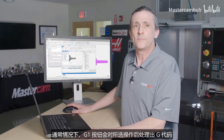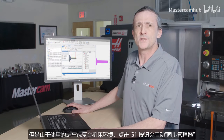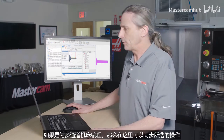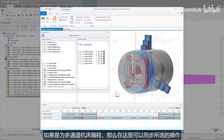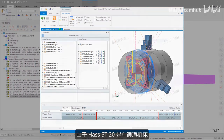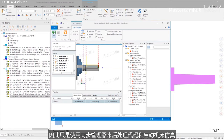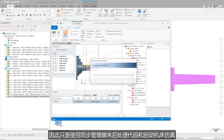Normally, the G1 button would post out the code for the selected operations, but since I'm using the mill-turn machine environment, the G1 button launches the Sync Manager instead. If I were programming for a multi-stream machine, this is where I would synchronize my operations to avoid machining errors or collisions due to conflicting turret movement. Since the Haas ST20 is a single-stream machine, I'm going to use the Sync Manager to post out my code when needed and launch simulation.